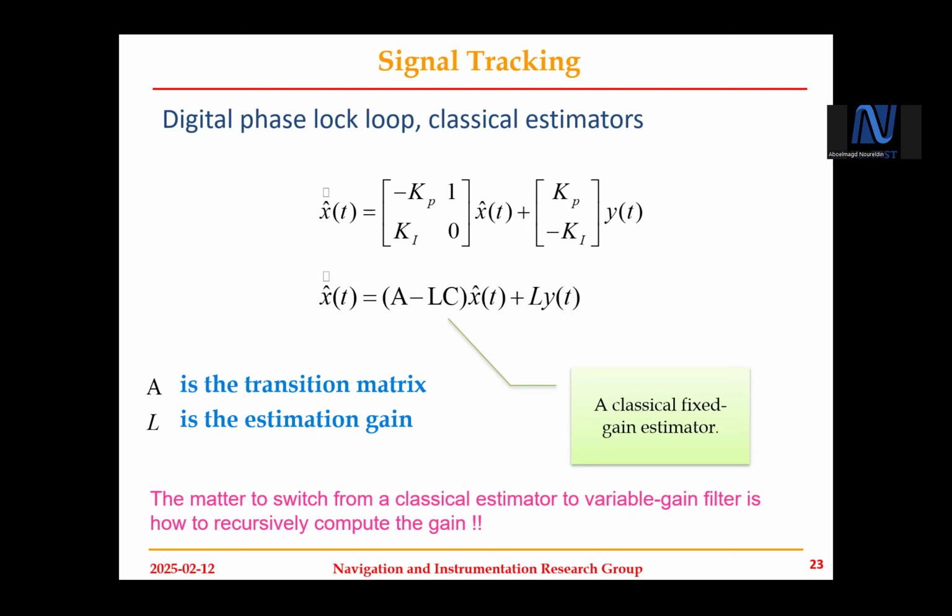But can anyone guess why we need, for example, up to 12 or even 14? Why do we need that in hardware? Because that costs money and adds complexity, right? So why shouldn't we just have, for example, 8 or 9 channels? Typically, we had 12 channels. Now I'm talking about GPS receivers only; with multi-constellation, you should have more channels dedicated for each.